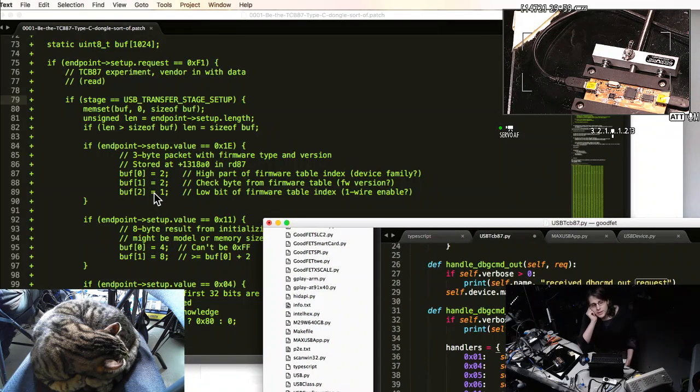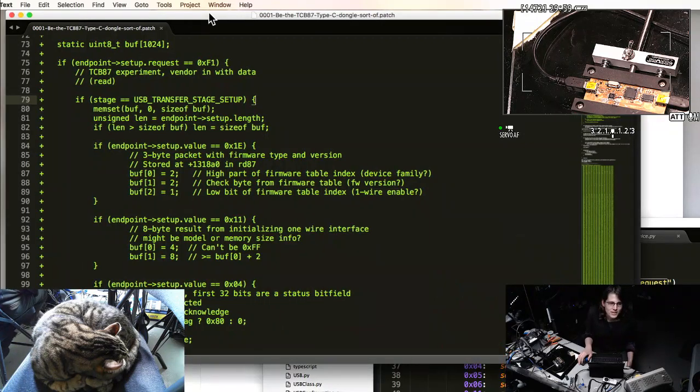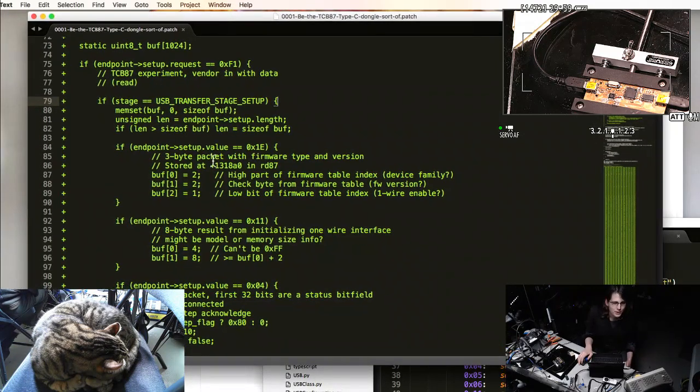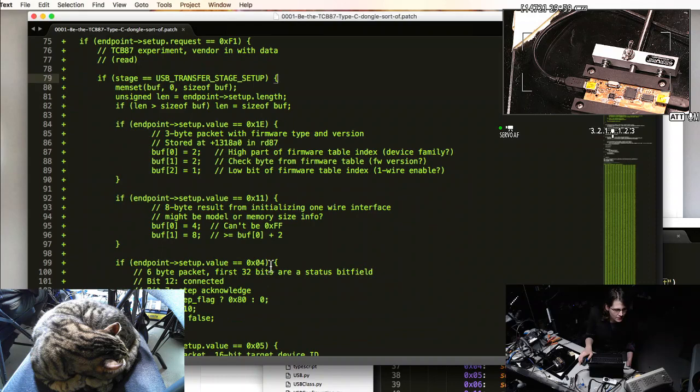There's a little bit of confusion between tables for devices and tables for different versions of the firmware that runs on the dongle, because there's a little bit of overlap between the two. The LC871 devices needed this particular dongle, and so the dongle firmware also has a flag indicating, like, does it support the new protocol? So it was a little hard to tell those two tables apart at first in the disassembly, I think.